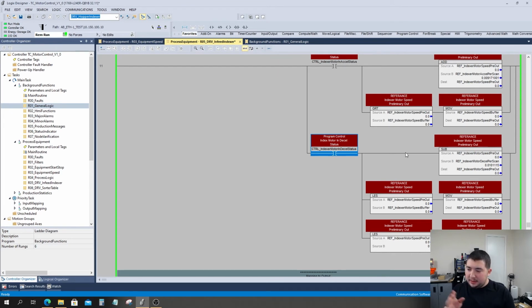And then the second part of this is if we're going down and we reach below 0, well, obviously our speed can't be minus, so we will taper off our speed to 0. So that's what this clear instruction does: if our value out is less than 0, then we just clear the value so it maintains that value of 0.